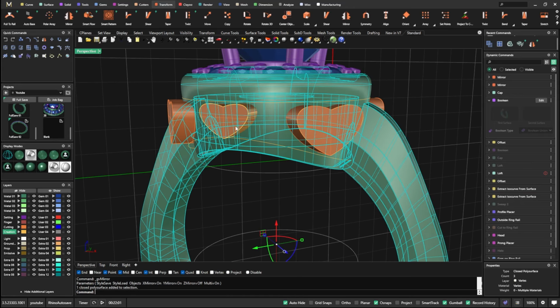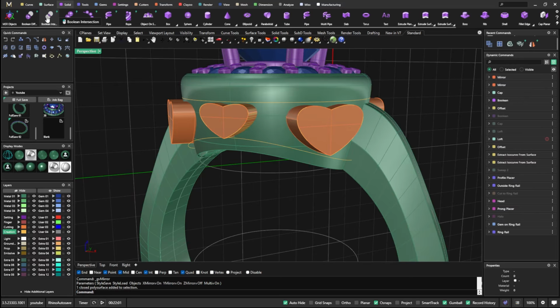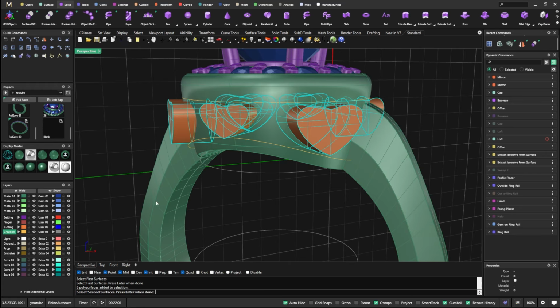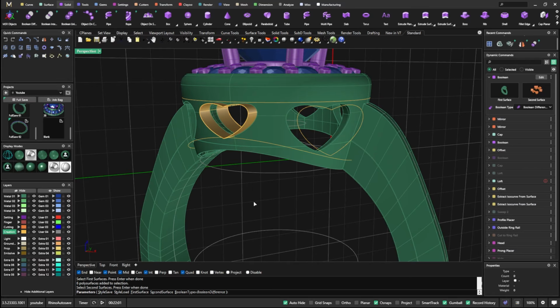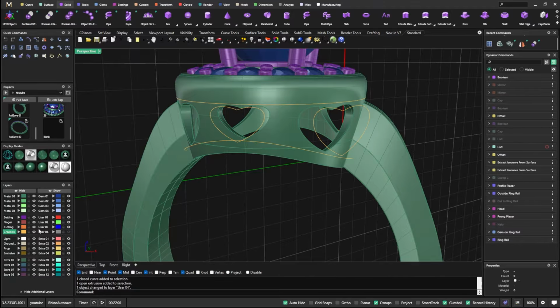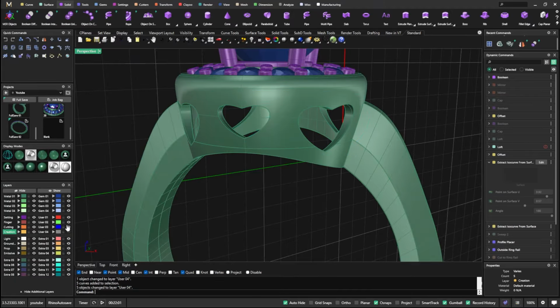Now we can take this, or we can go to solids, go to Boolean difference here, and click all our cutters, and then hit enter, and there we go. There's all our cutters, right? So we'll take all these, turn them to gray, and we'll take that yellow one here. Just the surface is all I want. Turn it to gray, and we'll turn all those gray off. Go ahead and grab all my yellow there, turn it to gray as well.